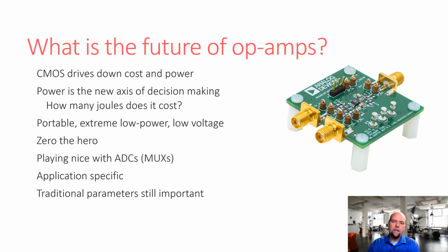So everybody tries to make marginal improvements on these things, especially when it comes to using these CMOS devices. Low power CMOS devices, sometimes if you sell an op amp and that op amp consumes 1 microamp of current just by being on, that's incredible. And if you're able to achieve that, people will probably let you slide a little bit on some of these other parameters, because they're really looking for that op amp that sips power. But still, you want to make all those traditional parameters as good as you can.